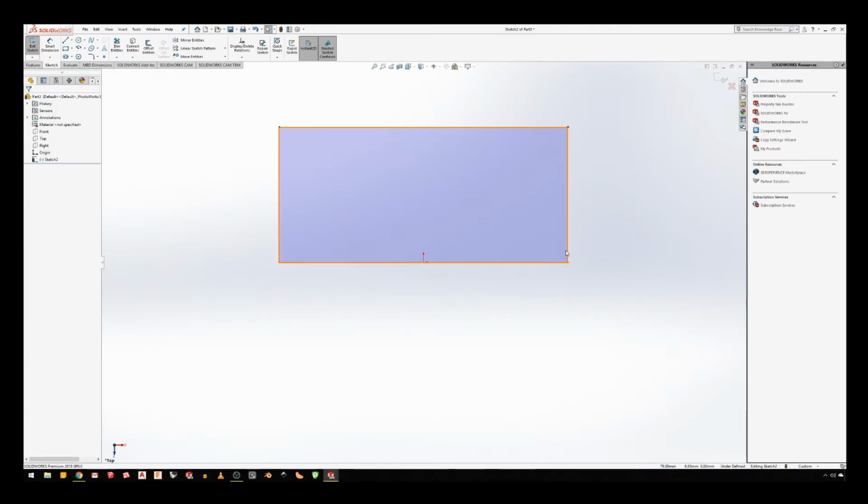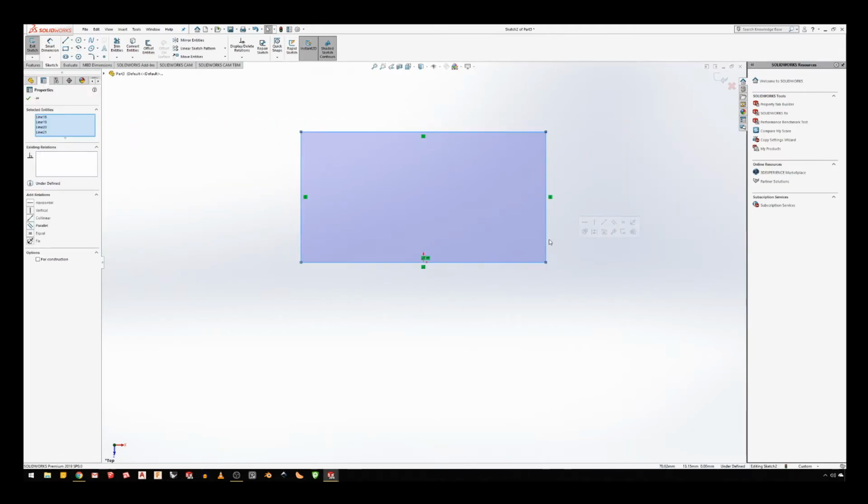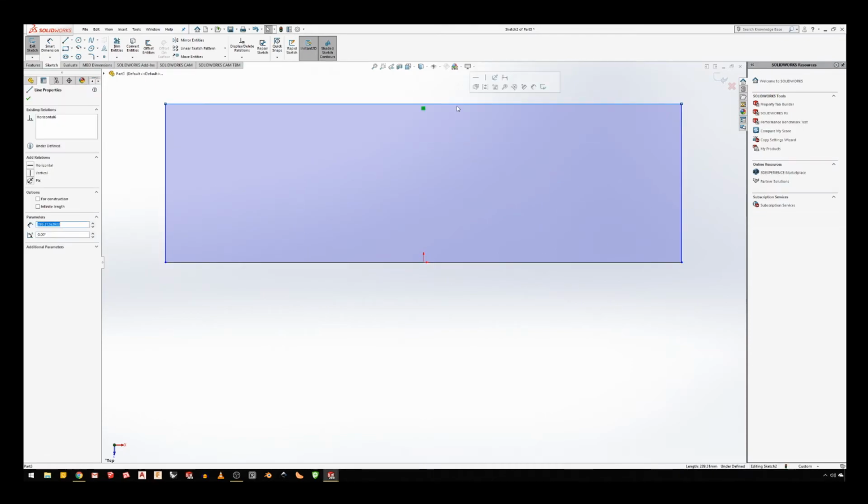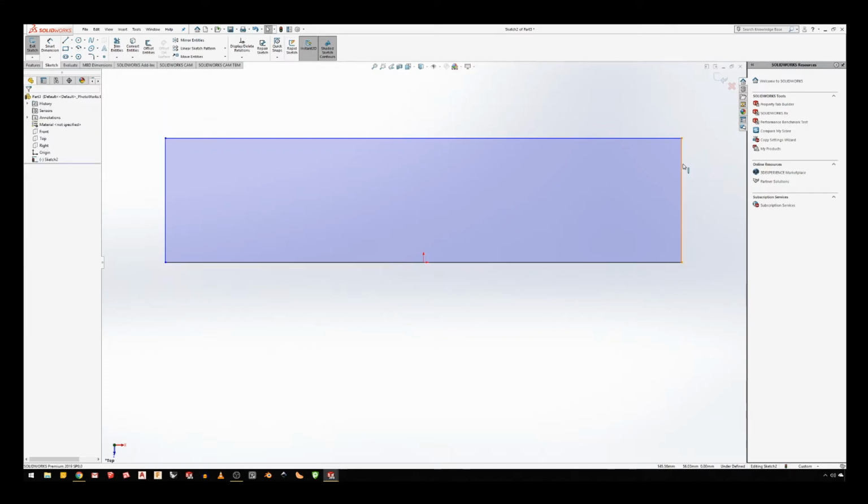So now we know that these horizontal lines are equidistant from each other. And we know that the bottom of our rectangle is constrained. But it's kind of a mess if you want to angle it, because now we've got tons of random constraints on here that we didn't ask for, like the vertical line constraint, another vertical, and a horizontal and a horizontal.